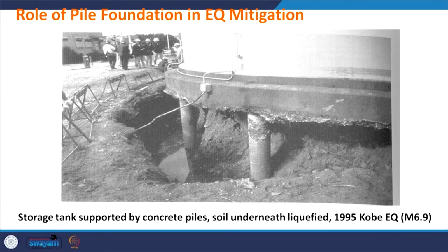The next slide is from the Kobe earthquake of 1995 in Japan, which was with a magnitude of 6.9, and this is an oil storage tank. You could see this tank is founded on pile foundations, and the soil below this tank got liquefied.